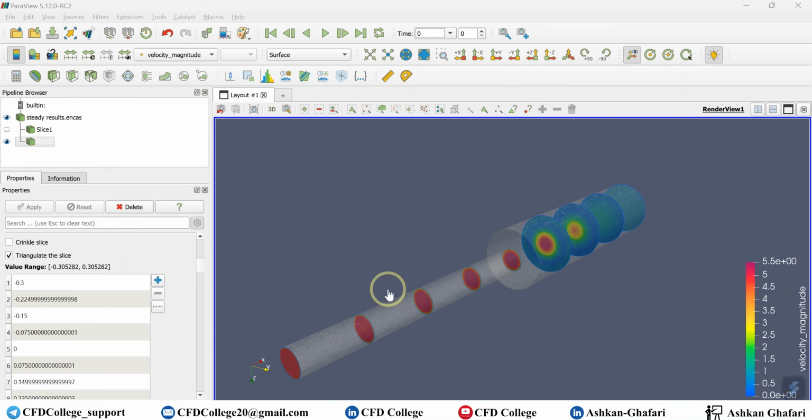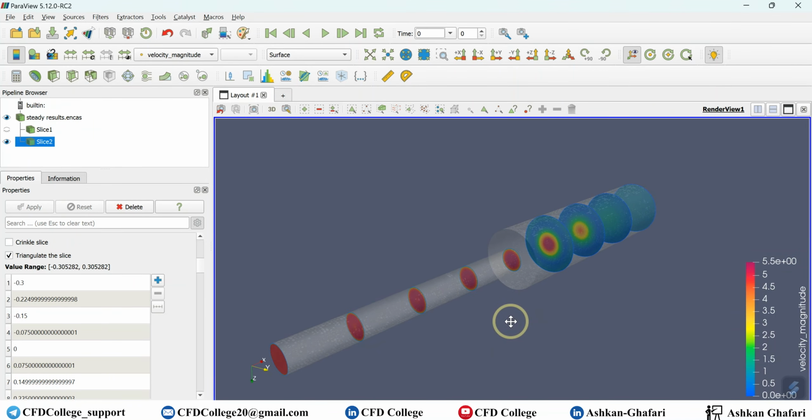It's obvious that you can use the same method if you have an external flow. You can change the color of the background. You can change the color map, as I did in the previous video. This is good, I think. You can create really exciting contours using this feature. So that's how we can create some contours using a slice.